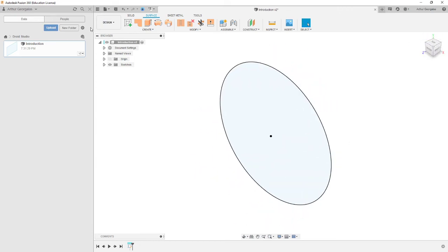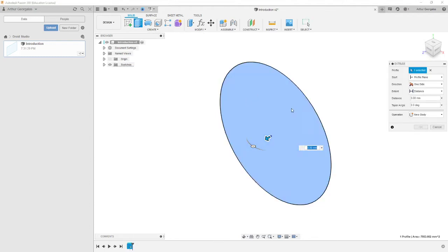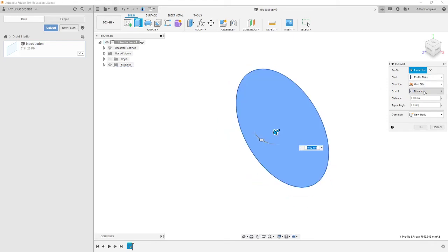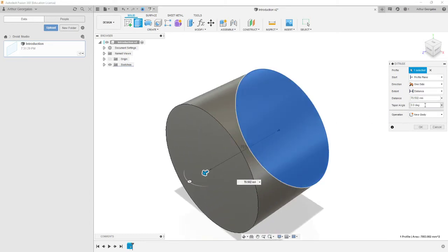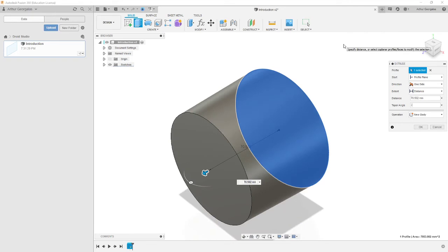That's pretty great. And when it comes to extruding, we don't have an option of a cut extrude or a boss extrude. It's all in one. So it already selects it because that's pretty much the only thing that's there. We get similar options to SolidWorks, distance, do we go up to an object? Do we go through all? Are we coming symmetrically? Are we starting at the plane or at an object? The distance, and here it's got what's called the taper angle. You might recognize this as a draft angle. So you've got 5 or -5 for a negative draft. It's all the same sort of thing.